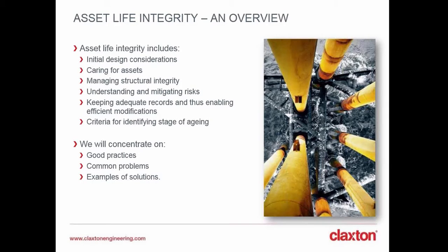It is because of these reasons that we think asset life integrity should evaluate the initial design considerations, which is what we have there on the screen. What was the original design life? What loadings was it expected to take? Which interfaces were considered key? Evaluating these against the current conditions might shed light on the root cause of issues with the equipment. So it's important to make that comparison.